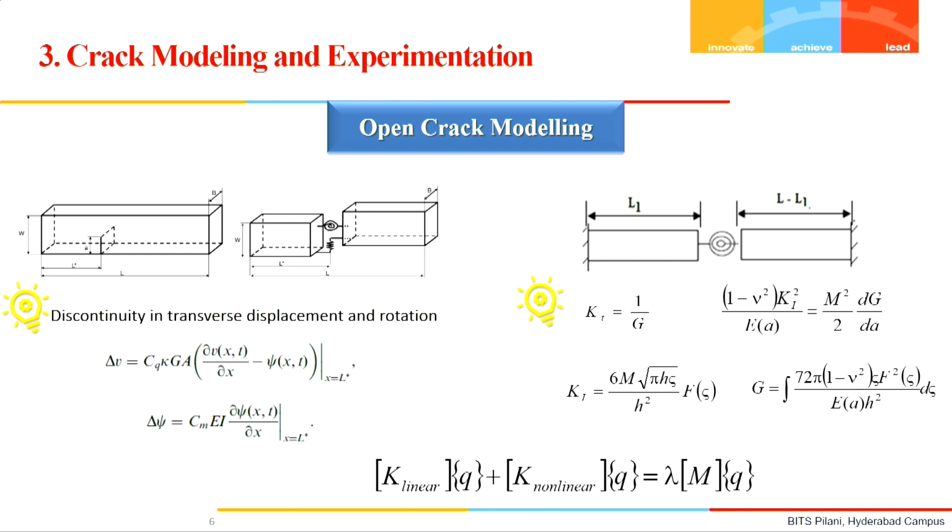So if we model it by a rotational spring, then as I told, remaining in the framework of linear elastic fracture mechanics and without touching the crack growth also, several beautiful outputs can be taken out for the structural engineers. That is what we are seeing.